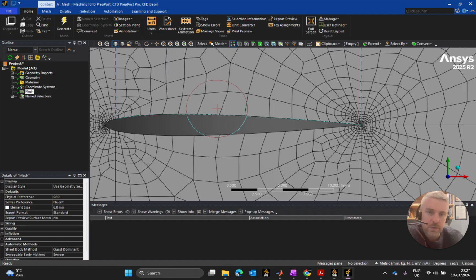But the idea on meshing is that meshing, without a doubt, should take up maybe two-thirds of all the time that you spend on your CFD analysis. A good mesh is absolutely fundamental. It's vital for good results, and of course a good, nice, tight geometry is a necessary prerequisite of even having the faintest chance of having a good mesh.